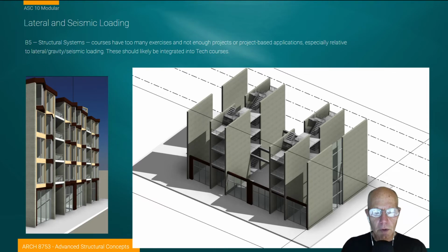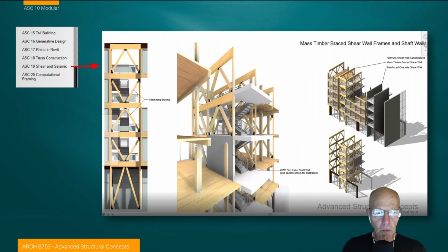And so some of our focus on this project is to really think in a structural way about the buildup of our componentry here. So here we have the idea of stairwells and shear walls and some other components, and I'll discuss that more in detail. Eventually we're going to come back and revisit this project, and we're going to use an adaptive component. We'll get into discussing some issues about seismic loading, and we'll look at creating a stairwell with bracing systems in it, and then using a gypsum board sheathing system in order to create fireproofing for it.